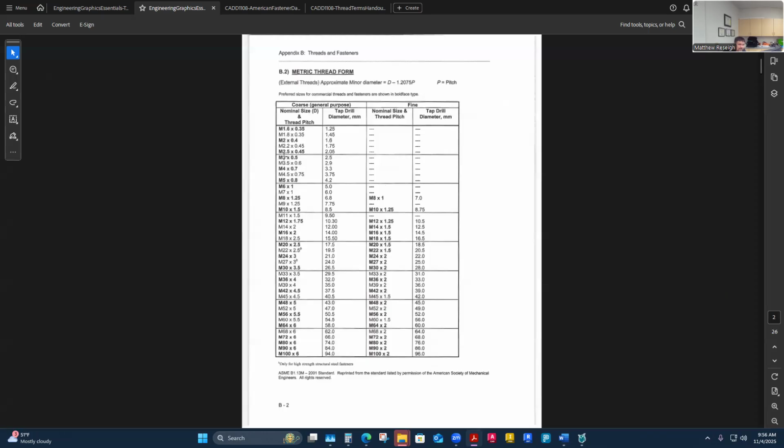So I'm an M3. If I look here, I either have an M3 or an M3.5. Mine's an M3, 3 millimeter. The next one is the pitch. So I don't use this. The thread note doesn't have an X in it, like M3 by 0.5, just this chart does. And it tells me that those are by 0.5, that's the pitch of this particular thread. And I wouldn't even have that option for a fine thread. So coarse is the only one. So to me, it's going to be M3 dash 0.5.